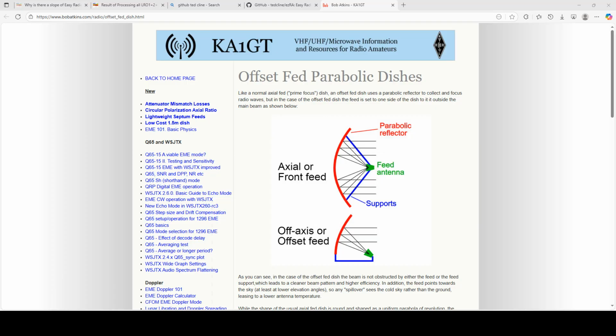You can design it so that the feed comes out on a horizontal arm like that, which, because it's only half a parabola, means that you can use the arm to sight along to aim the dish. So you don't have an issue finding what you're pointing at, because you've got an excellent sighting arm for that purpose. He's making a 3-meter one, so I've no reason to think it won't work as long as he makes it strong enough.